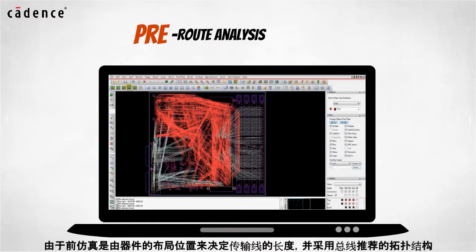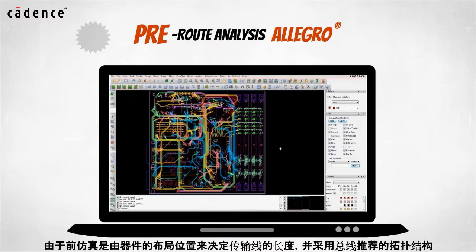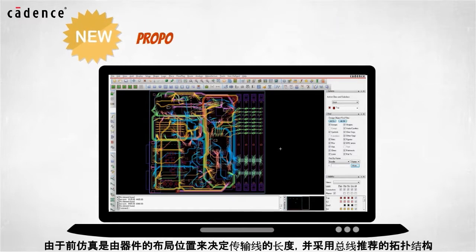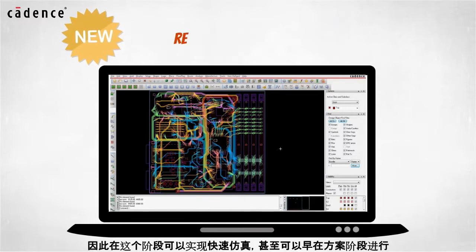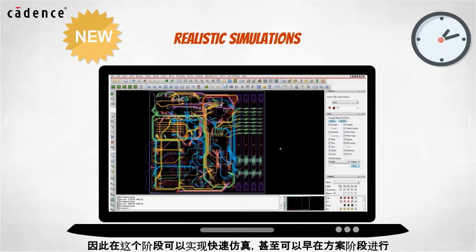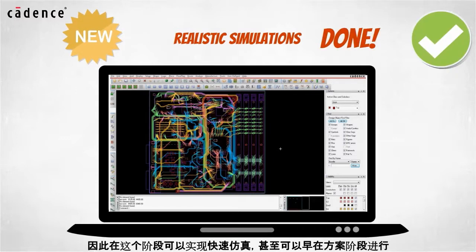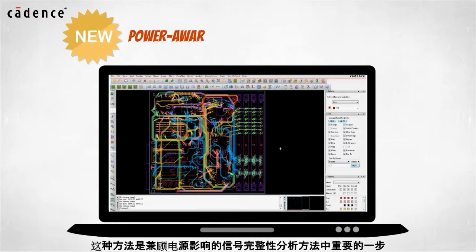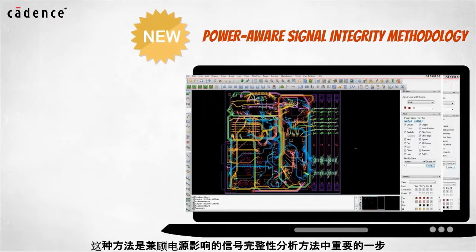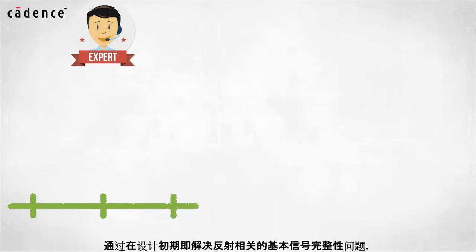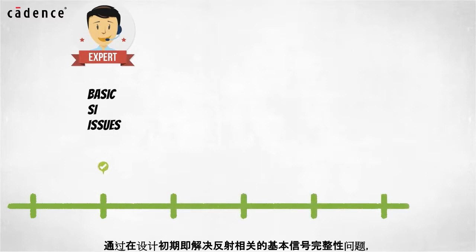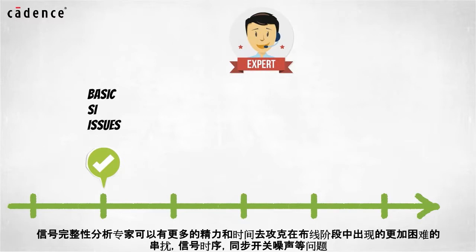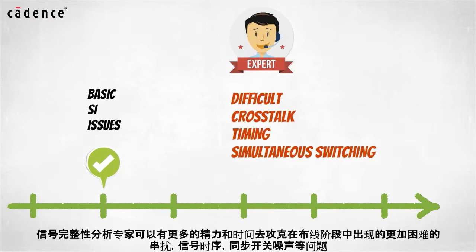Since the pre-route analysis uses transmission line lengths based on the Allegro component placement and the proposed bus routing topologies, realistic simulations can be run very quickly at this stage before routing of the PCB even gets started. This approach is an important step in a power-aware signal integrity methodology. By addressing basic reflection-related SI issues early in the design cycle, signal integrity experts are freed up to focus on the difficult crosstalk, timing, and simultaneous switching noise problems as PCB routing tasks progress.